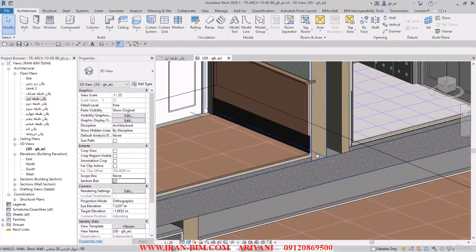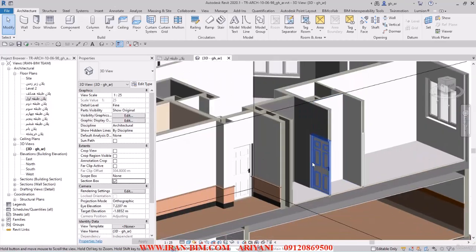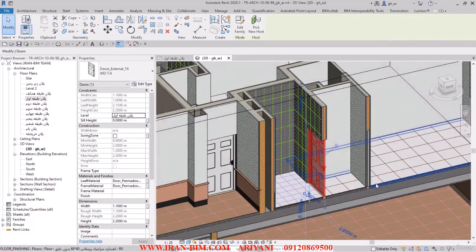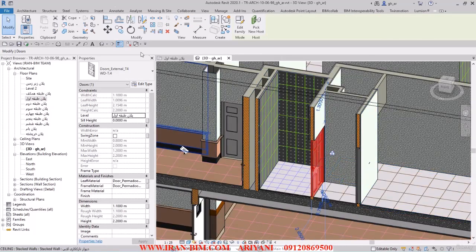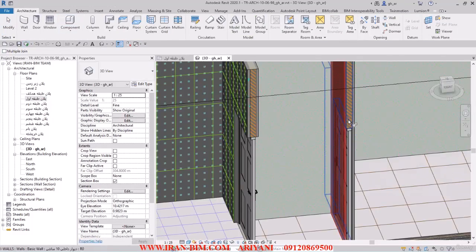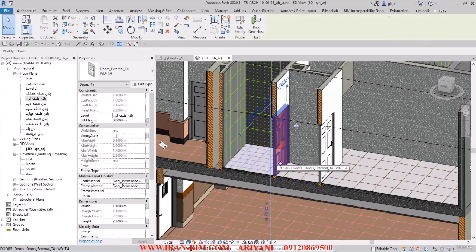So it's basically just the points that I mentioned earlier that can help you make these out precisely as you want. Although we have to discuss the bathroom doors as well later on when we get to them. We usually draw the bathroom doors 5 centimeters higher. Oh, it seems like I haven't joined these parts, so let me just go here. So this one with this one here. All right, there we go. And because the doors have to line up, we have to move both of them. So I go here and I move this 5 centimeters upwards.